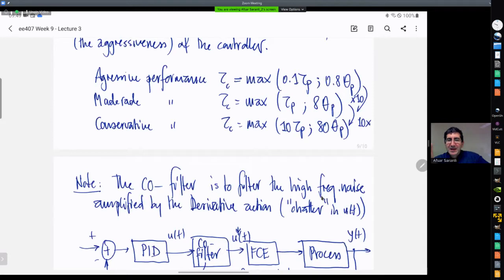But the time delay model that we introduced has an exponential function in the numerator. An exponential function cannot be represented exactly by a finite polynomial. It can be represented by its Taylor series expansion with an infinite number of terms. That is why time delay is often characterized as an infinite dimensional linear system.